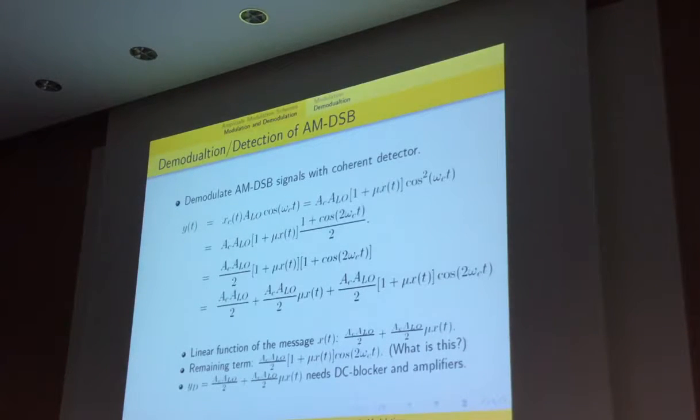High pass, I heard high pass just now. Low pass. Anyone want to use a band pass? So you have used all three types. One of them must be correct, right? Because our useful message is located in a low frequency band, we should use a low pass filter to retain this portion and reject the high frequency component.